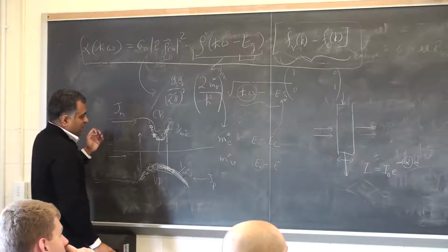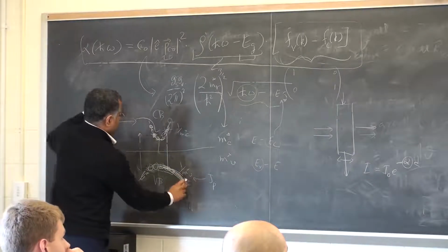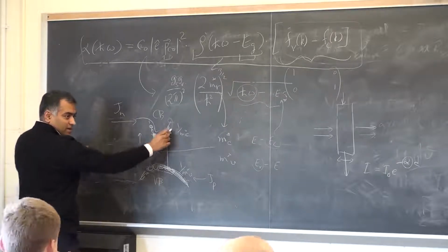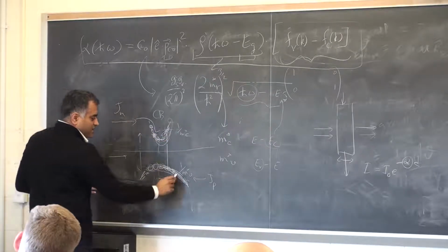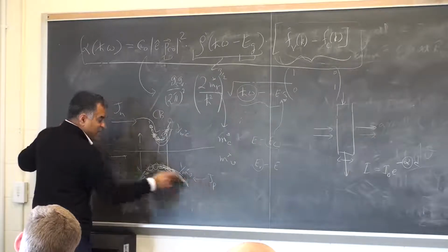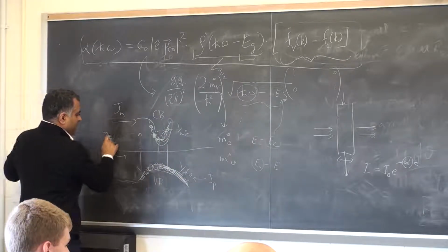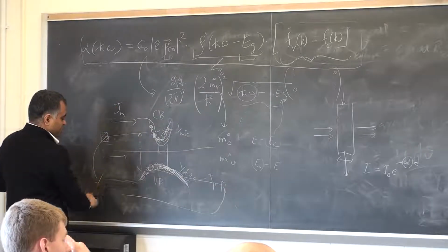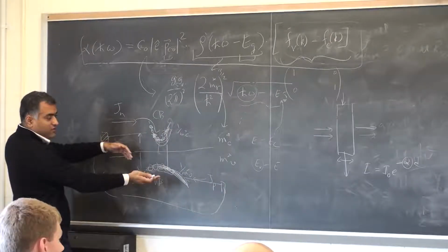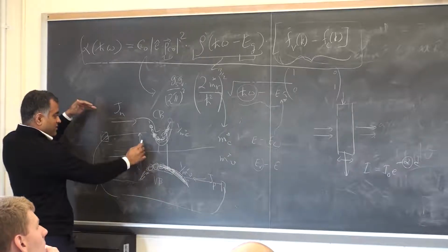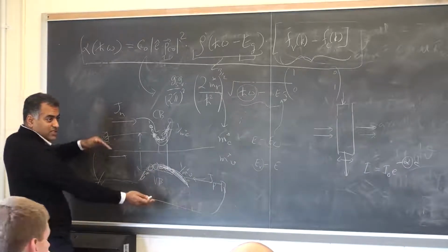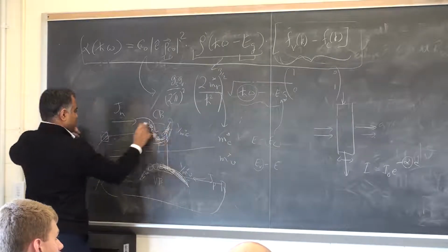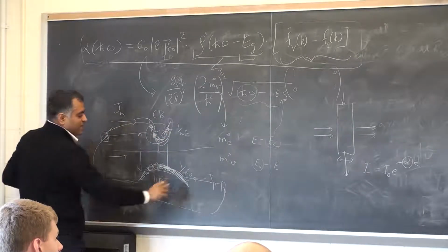Now, in a PN diode, what I'm doing is I have formed two ohmic contacts, one to the N band or the conduction band, the other to the valence band. A metal is connected to this, a metal connected to that, and they are now connected through a battery. So now I have two Fermi levels. I can define two Fermi levels: one says the conduction band is in equilibrium with this contact, and the other says the valence band is.